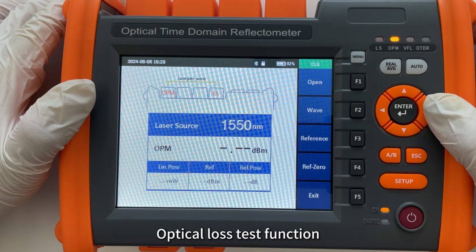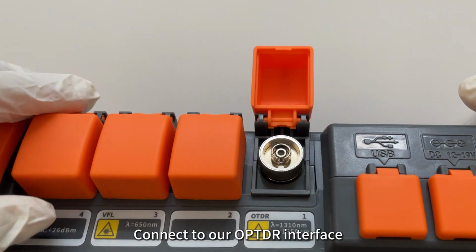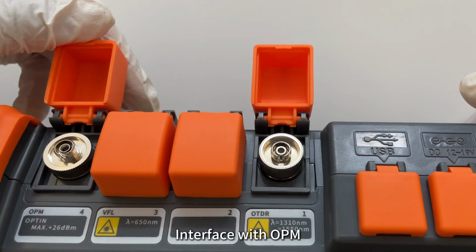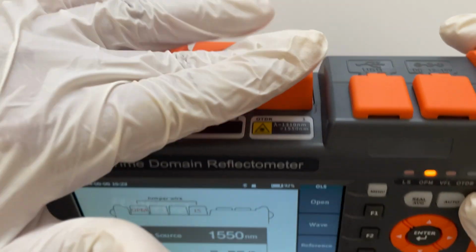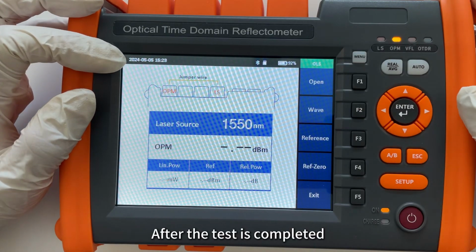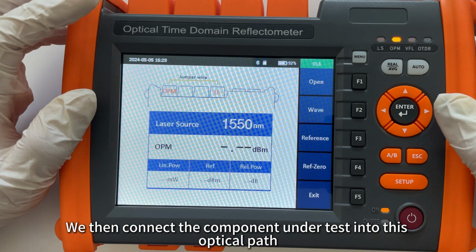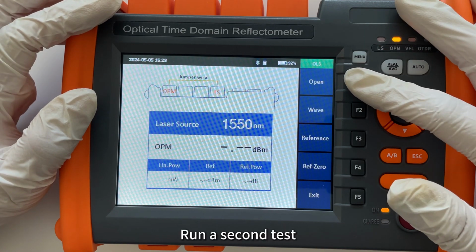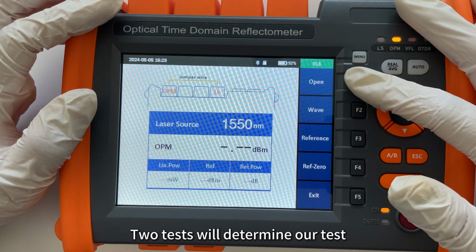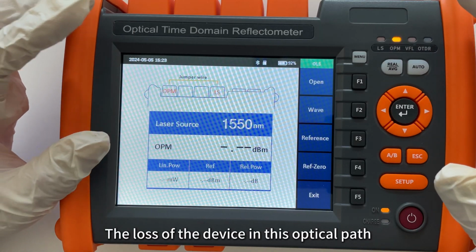Optical loss test. For the optical loss test function, we need to first connect the jumper to our OTDR interface and the OPM interface. Test according to the prompts. After the test is completed, we then connect the component under test into this optical path and run a second test. The two tests will determine the loss of the device in this optical path.